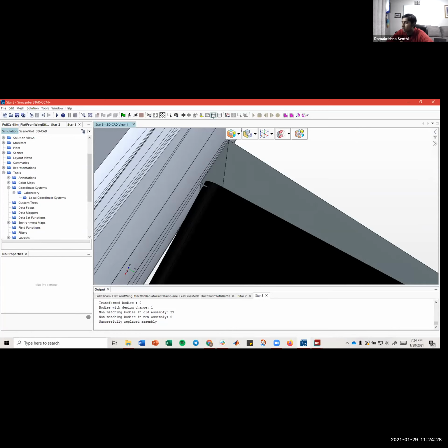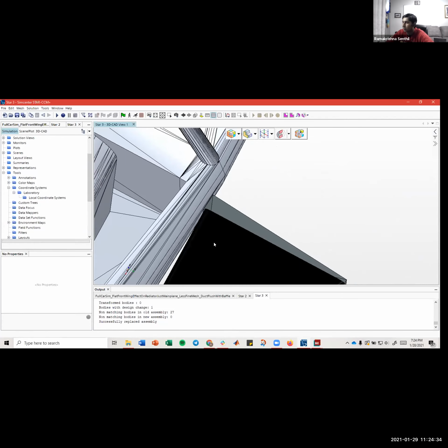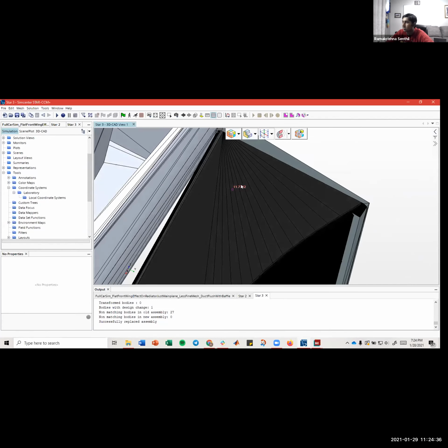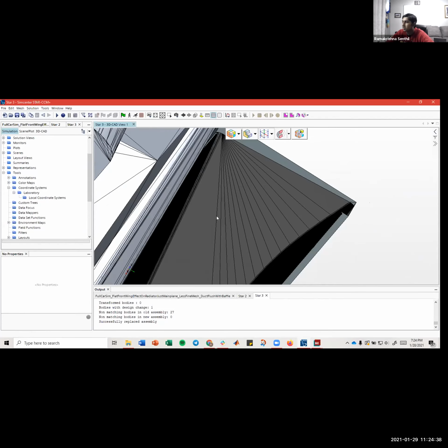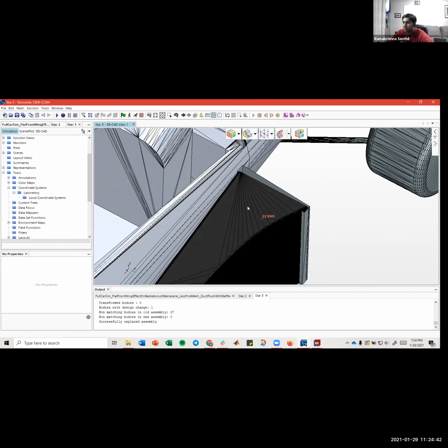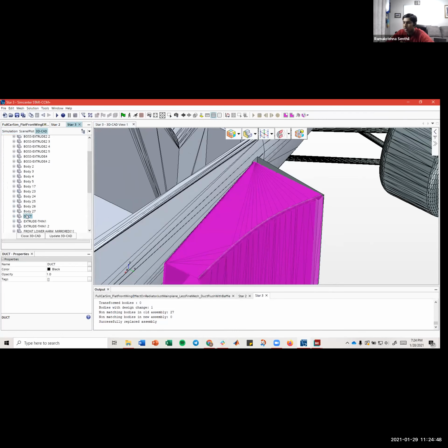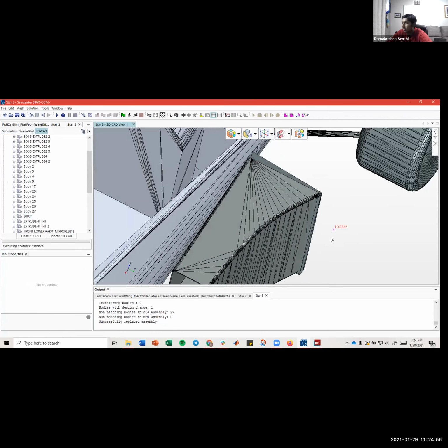And then you can click this top thing here to show the mesh, and it'll show the parasolid geometry lines. Also, this black color makes it really difficult to see lines on it, so we can change that real quick. Go to 3D CAD, duct, and then change the color here. Let's say gray. Yeah, that's a lot better.